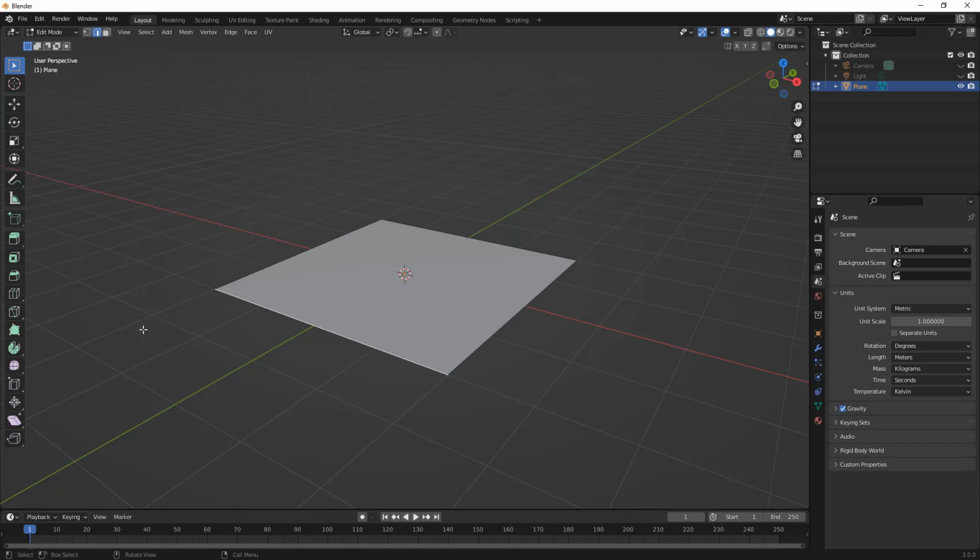So the first thing that we're going to do is we're going to use the loop cut option by left clicking, and then we simply need to place the cursor in an orientation, and whenever we see a preview, that's going to be the orientation in which the cut's going to go. We're going to click, and I'm going to place a couple of these, dividing this face up fairly quickly into even sections, because every time we use this loop cut option, it's directly in the middle.